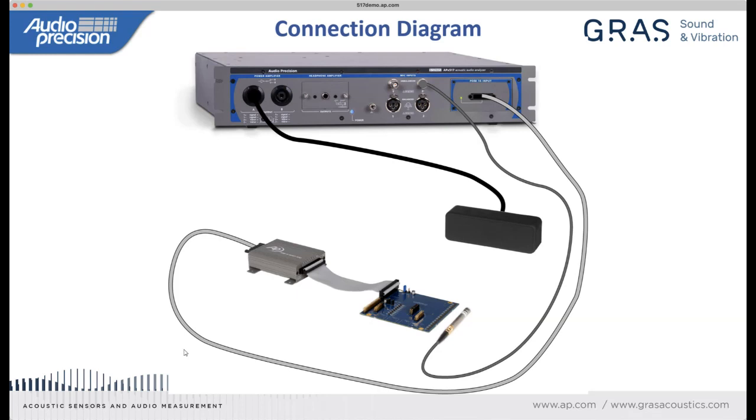A little advantageous detail: at a 1/4-inch size, a free field and a pressure field microphone have a flat frequency response to 10 kilohertz. When a 1/4-inch pressure field microphone is 90 degrees incident to the sound field, it will actually have a flat response to 20 kilohertz even in a free field. So that's sort of another advantage. I'll say the smaller the microphone, the more flexibility you have with how it can be positioned and used in different sound fields.